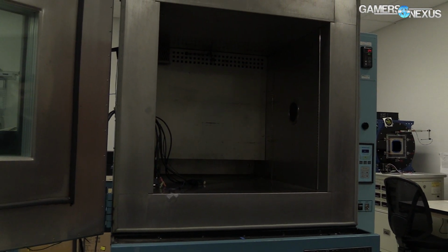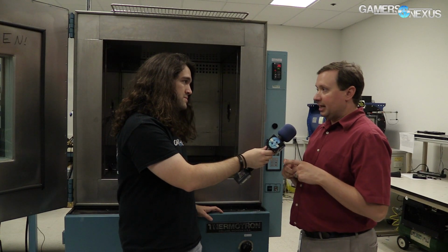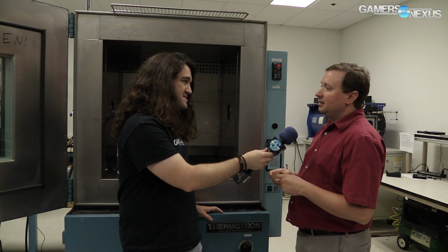We use a thing called a thermal test vehicle, which is an actual processor made by Intel. It goes into an actual processor socket and has the same mounting as a heatsink. You can attach a heatsink to it, and then the wires come out of this thing, go to a power supply, and you turn it up, and it's a heater. It's just a heater chip. It doesn't actually compute. Right. And then I can say I want 100 watts, and then I can measure the temperature at the top of the die and its temperature differential, and then calculate how well the heatsink is working.